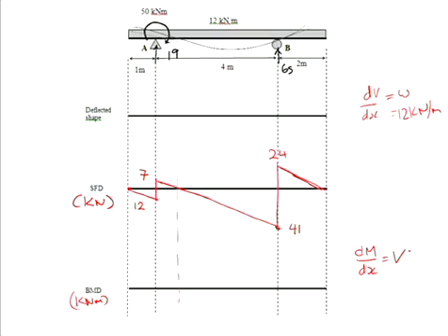So, where is my bending moment 0? At a cantilever tip, 1, 2, and it may be 0 somewhere else, but I don't know where. So now I say to myself, negative shear force, upward slope, positive shear force, and I mean the value. This is a negative value. I have a negative value of shear force. It means my slope. So this, as well as being V, it's also dM/dx.